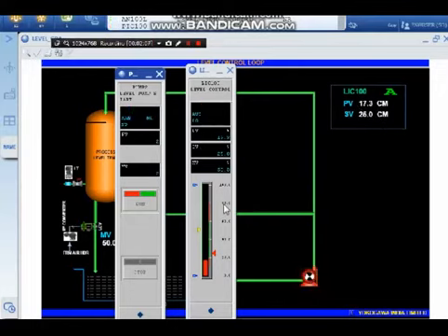Since tuning parameters may differ, KP, that is proportional gain, integral time, and derivative time change, so this may not happen exactly. It may exceed, and again it may come down, like the PID responses we have seen. So it reached 30, 36 now. We can also change the tuning parameters with this particular system. We can see that this output is coming.